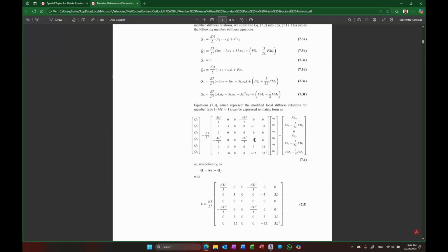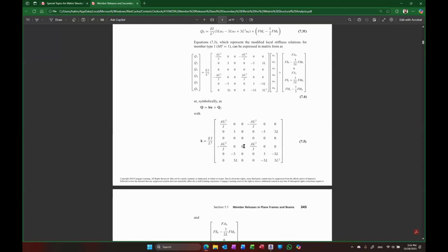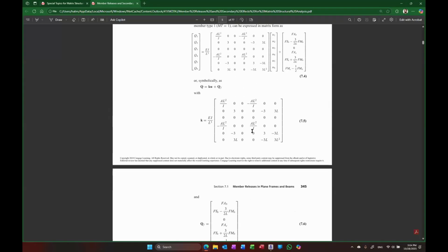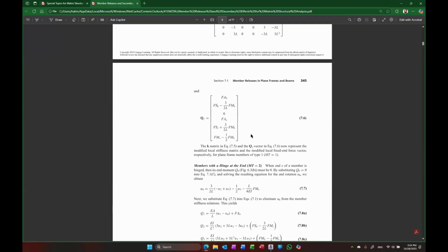And again, I think I covered a little bit about how the element matrices change as we add hinges, with these zero rows and columns being introduced as we add more hinges. And we talked about how these matrices on their own would never be able to, they wouldn't be invertible, they would be singular, and how adding multiple of these elements might end up creating a matrix that is actually invertible.